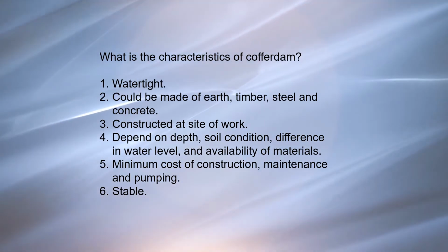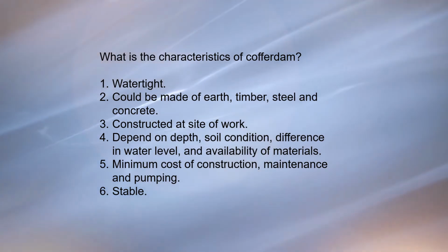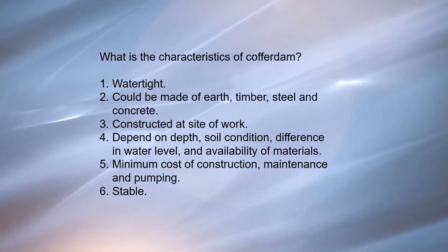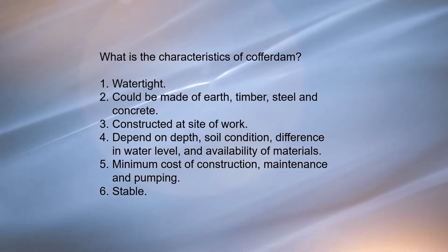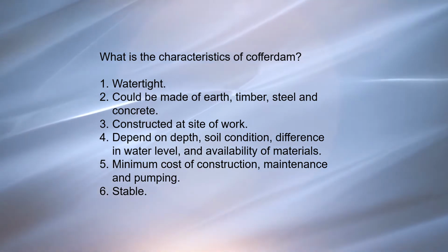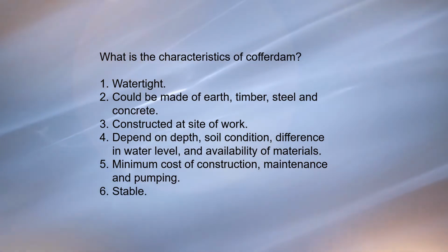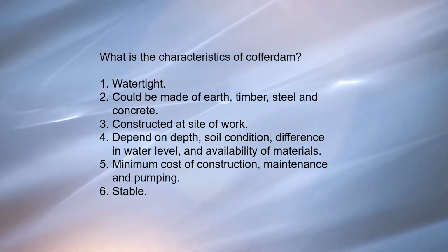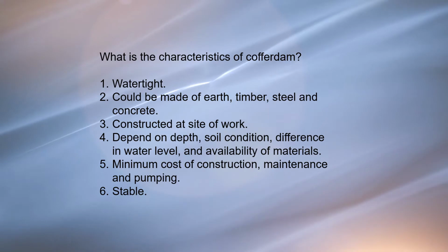What are the characteristics of a cofferdam? Number 1, a cofferdam should be reasonably watertight. Groundwater or water lying above ground level should be excluded. Number 2, materials for a cofferdam could be earth, timber, steel, and concrete.